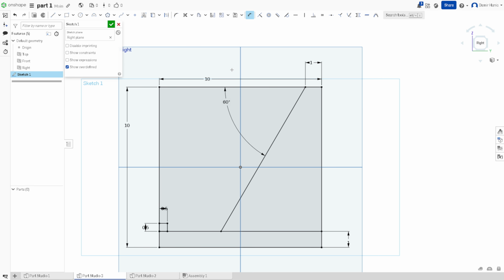So let's do that. We're gonna go to 3-point arc, and this means that you're gonna add 2 points, and then the middle of the line you can actually create like a half a circle. Let's add this point here, and you see how you can change it. So we're again gonna dimension this. Add this, it's gonna be 1 centimeter. But this, I don't like that this is so thin. It can break easily. So we're gonna modify this radius and add maybe 5. Not like this, but it doesn't matter. This is just how you're gonna see your dimension.